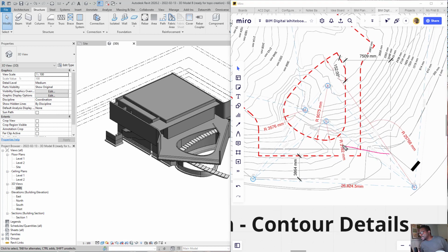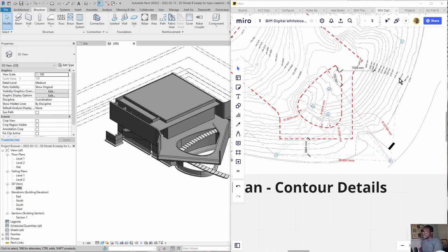And you can see the curved nature of these contour lines curving to show you where that stairs would go. So it's going to be very important that you trace the exact curvature of these contour lines and heights so that your stairs will land nicely there.